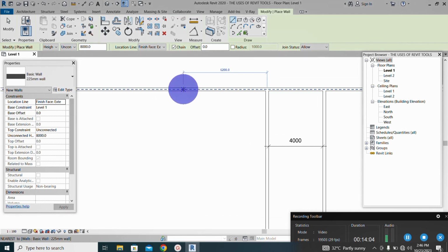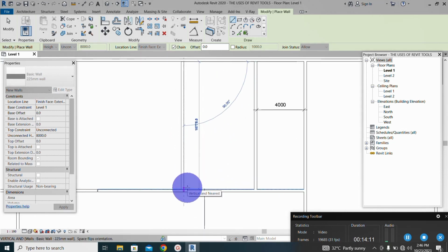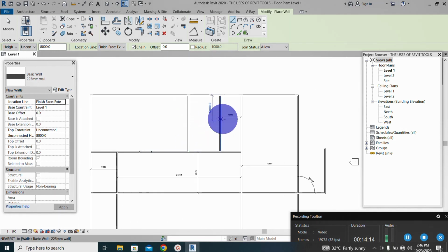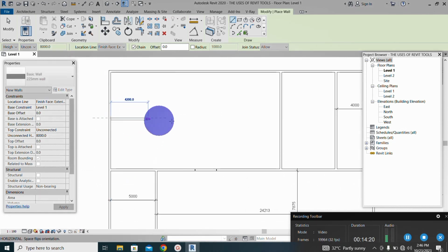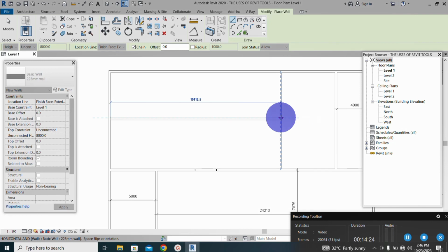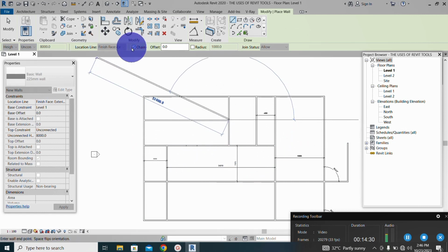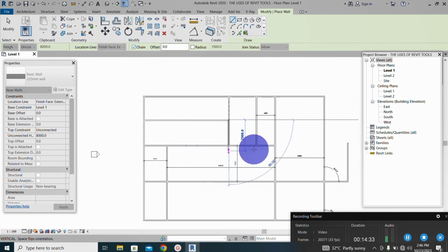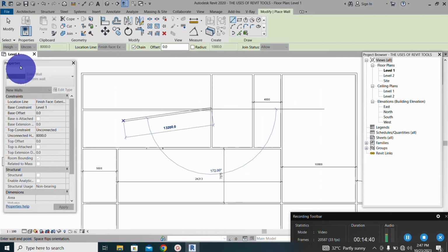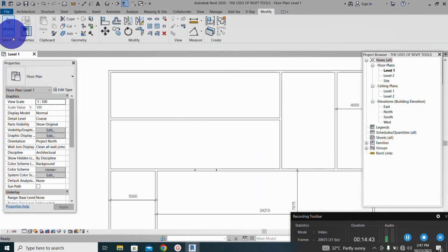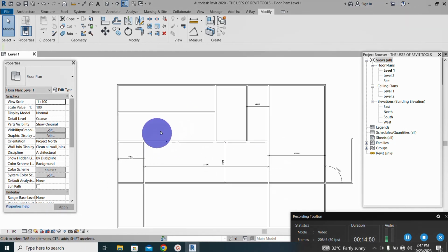Now, I want to create the wall here. You can see. Boom. I've created a similar wall. I can decide to create that wall here. You can see. Then, because our chain is active, you can see from this option bar here is active. That is why it's like this. You can exit by pressing escape or by clicking on your modify to exit the command. That is how create similar works.